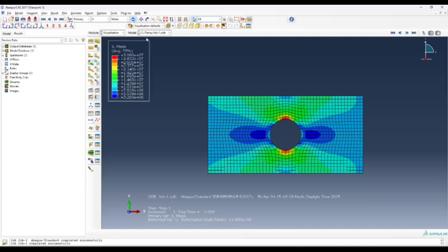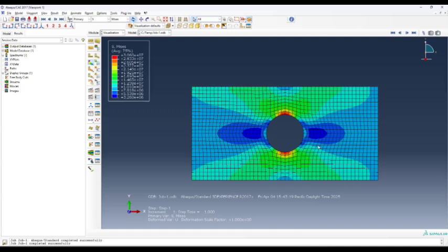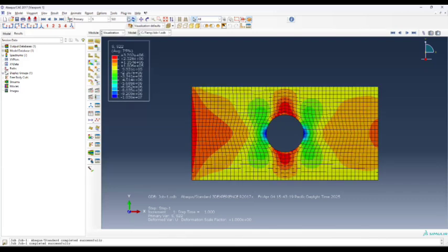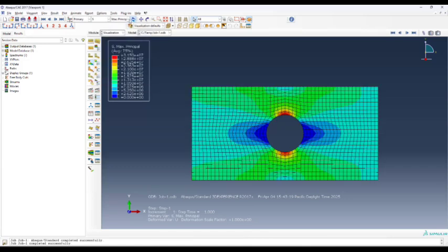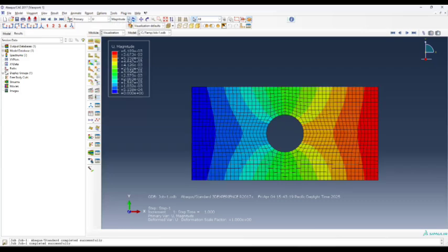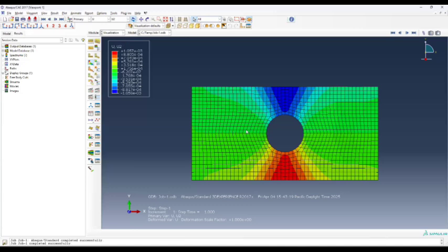But what we do see is deformation, we see stress distribution. So obviously around the hole, there's going to be stress concentrations. We can visualize that here. We probe it, can figure out what we want from it. We can check. So S is going to be our stresses, so we can check S11, kind of plot it all across at different points, S22, that's in the y direction. S33, obviously, no 3 direction at this point because it's a flat plate. Next, principal, Von Mises stress, so on and so forth. You're familiar with that. Now we can check our displacements. Obviously, at this end, very minimal displacement, maximum displacement going to be here. All very low quantities. All of our displacement going to be in the one direction, really nothing or something very low in the other direction.